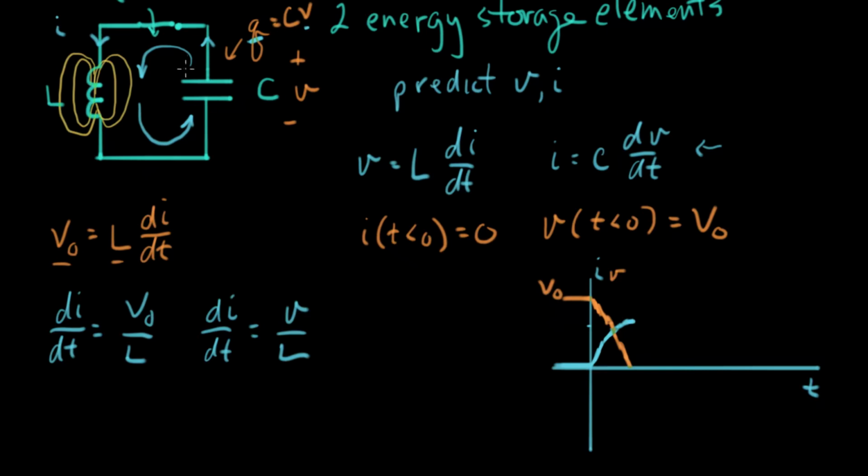Okay, what that means is that charge is continuing to flow in what direction? In this direction here. Charge is continuing to flow like this. And what's happening now is we're getting excess plus charges flowing on this side of the capacitor. So we're actually building up positive charge on the bottom plate of the capacitor. And what that means is the charge is reversed, so the voltage is reversed.